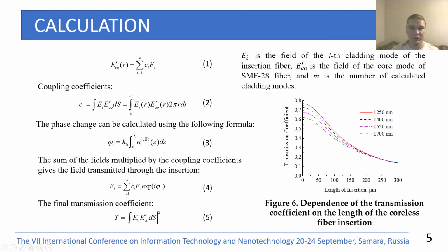The electromagnetic wave enters the insertion from the standard fiber, so we decompose the field of the core mode of the standard fiber into modes of the insertion fiber using Formula 1. Coupling coefficients can be obtained by Formula 2. The phase change can be calculated using the third formula. The sum of the fields multiplied by the coupling coefficients gives the field transmitted through the insertion.